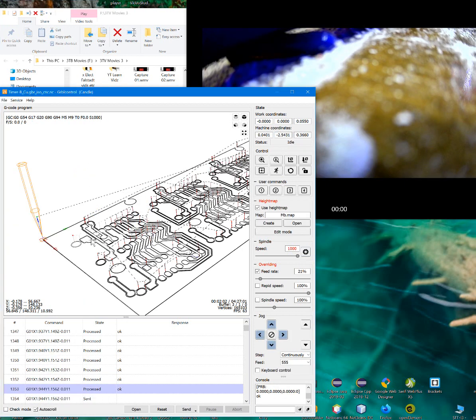I'm having to dink with this a little bit. I just got through adjusting the Z-axis up a little bit, by about 1.7 mil, because it was just routing too deep. And also my bit, I guess I didn't tighten it enough, but for some reason it ended up being like 10 mil too shallow. So I don't know, I'm going to have to check into that. I'm still in the process of looking at it.